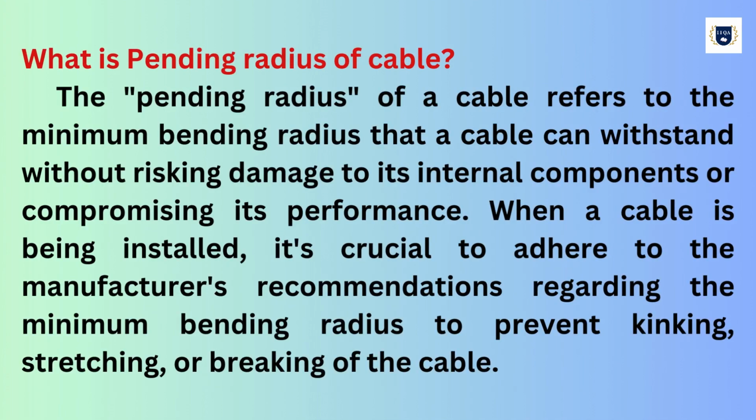What is bending radius of cable? The bending radius of a cable refers to the minimum bending radius that a cable can withstand without risking damage to its internal components or compromising its performance. When a cable is being installed, it's crucial to adhere to the manufacturer's recommendations regarding the minimum bending radius to prevent kinking, stretching, or breaking of the cable.